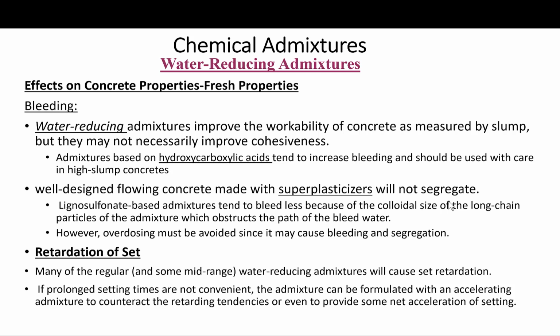Okay, so with regard to the retarding of set, many of the regular and some mid-range water reducing admixtures will also act as retardant admixtures. So if prolonged setting times are not convenient for whatever your situation is, the admixture can be formulated with an accelerating admixture to counteract the retardant tendencies, or even to provide some net accelerating effect on the setting if needed.